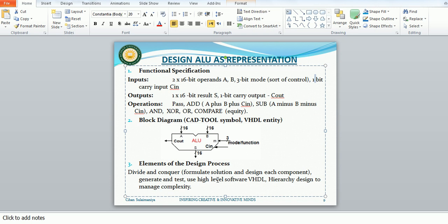So what I want you to do, maybe I will give you subtraction. What does subtraction need? Of course you need two inputs and one output, but what else? What other modification do you have? Do you need cin or not? Do you want cout or not? Of course no cout for subtraction. Okay, so what about the signal? If you subtract two numbers and there is a signal in minus, what are you going to do?